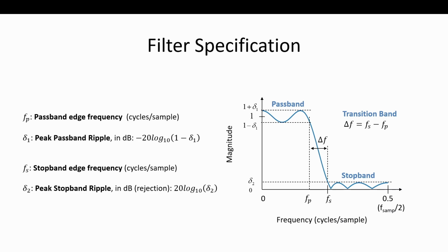You can kind of see with FIR filters, a simple way to look at it is a weighted moving average. So does that mean more coefficients and longer? That's right. More coefficients, longer duration, longer delay, everything longer, right? The idea of a weighted moving average is an easy way to understand filtering. Just an average is a filter, a moving average.